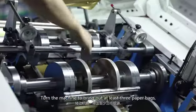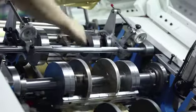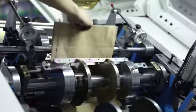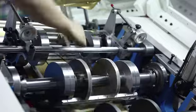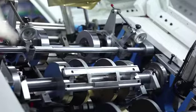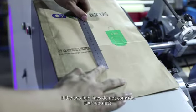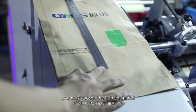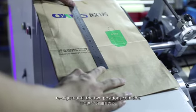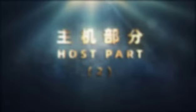Turn the machine to bring out at least 3 paper bags, and then check whether the position of the first fold line is correct on the third paper bag. If the 2 fold lines do not coincide, you must loosen the hub again and readjust until the two positions coincide.